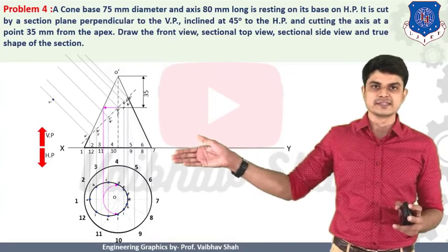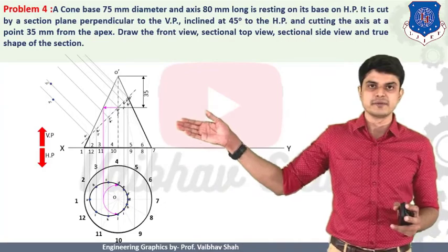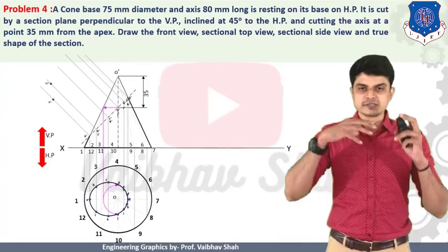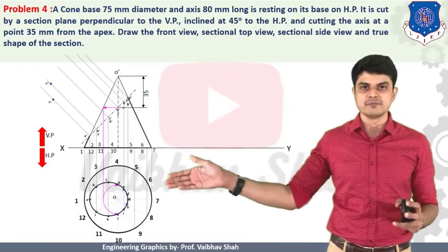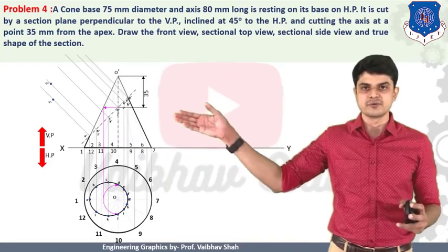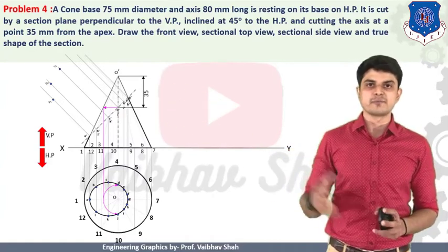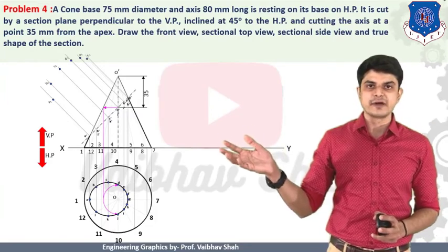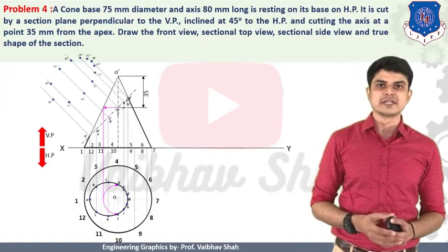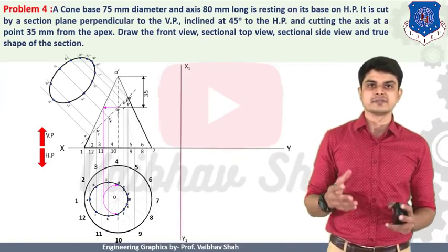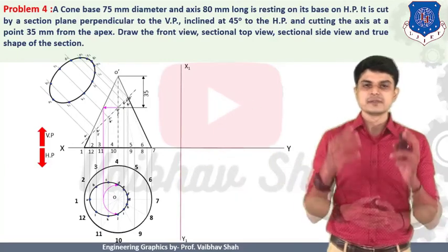Thereafter similarly you should take the distance of your point B from your XY line. You can similarly generate point B. And similarly you should follow the same process. You should take the dimension of each of the points from this XY line and below this object, and you should put the dimension from your cutting plane line onto the respective line in the same direction. You can have the different points generated like this, and after getting these points generated, you should just simply connect these points in order to have your final object generated. This is nothing but your true shape of the section generated. So this is nothing but true shape of section, and this is what a sectional top.